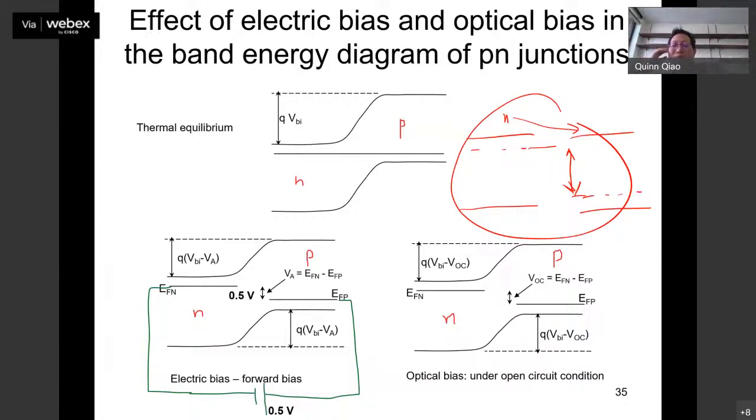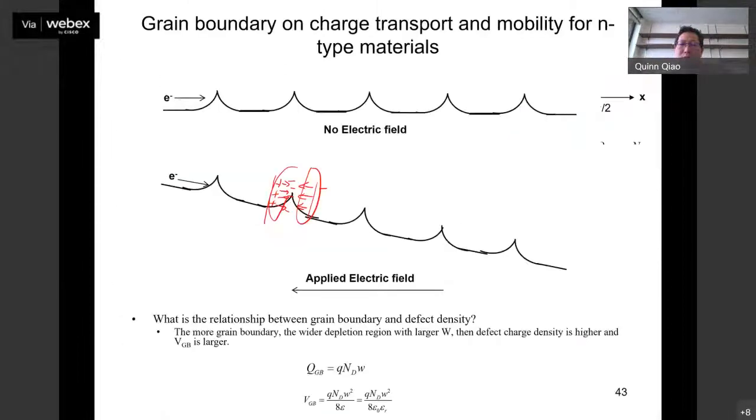That's where the charge transport is. So you don't care about inside the N, from one position to the next position. That's why you add the electric field there. You want to direct all the charge transport for solar cells from P to N, for diodes from N to P. So if we are moving from top to bottom, not from left to right, then we are finding this type of notch at the grain boundary that you have shown in slide number 43.